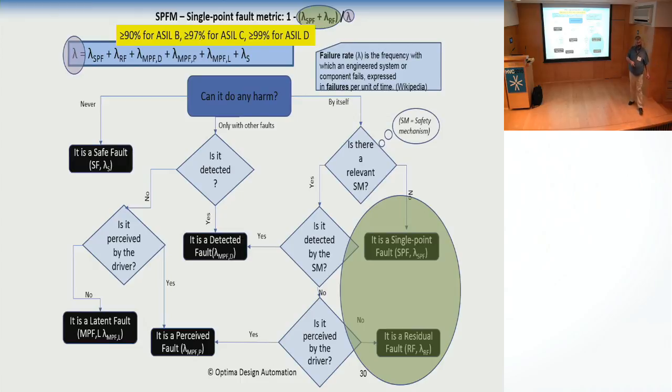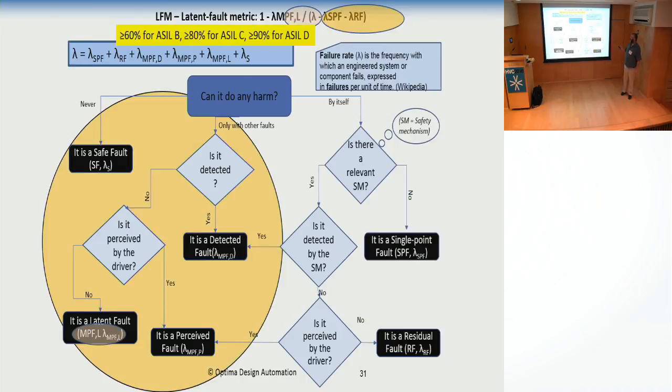So, good point, and you should not do that, but if you are doing things in good faith, this is a good metric for yourself to see how well you are safe. Similarly, I want to see how many latent faults there are out of all the non-critical faults. How many of the faults that don't kill you are lying there lurking and will catch you later. Again, the goal is to be under 10%, and yes, you can always dilute things.